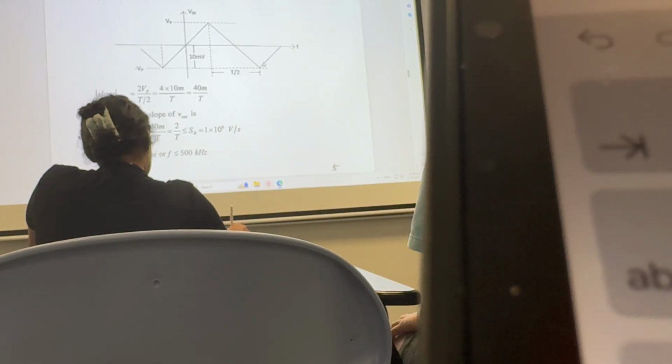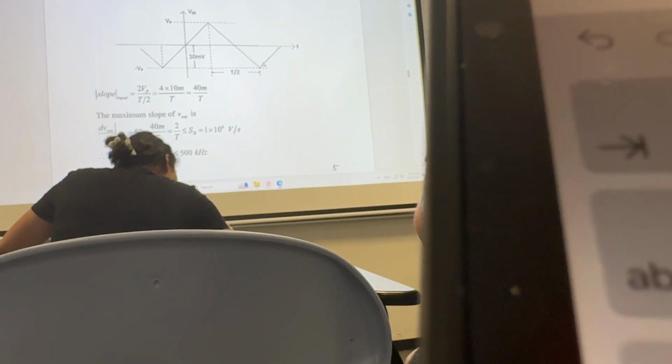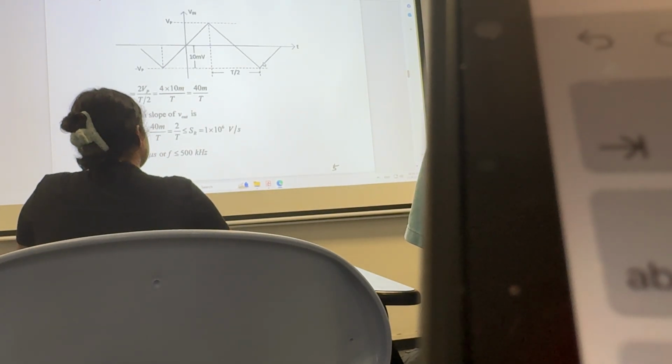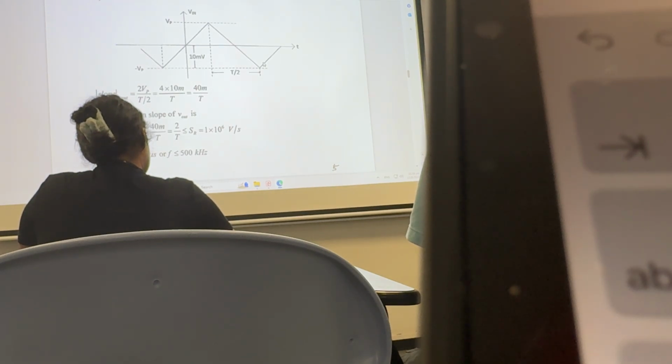When you further increase the frequency, it will also be a triangle. Right? Distortion in a triangle is also the same, but the magnitude is reduced. Slew rate distortion to the sine wave, you see from sine to triangle. A triangle is still a triangle, and they distort, but the magnitude is reduced. Okay, interesting, right?